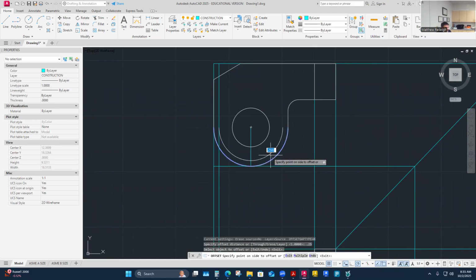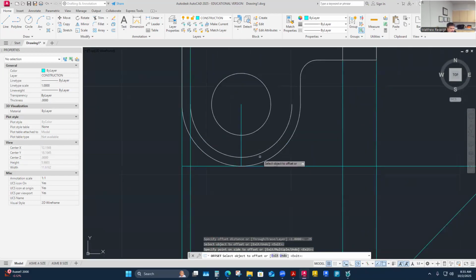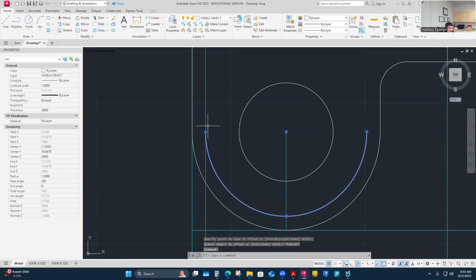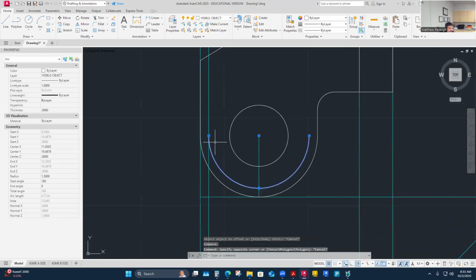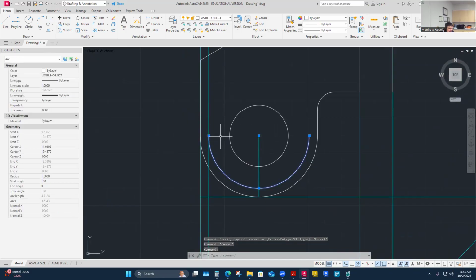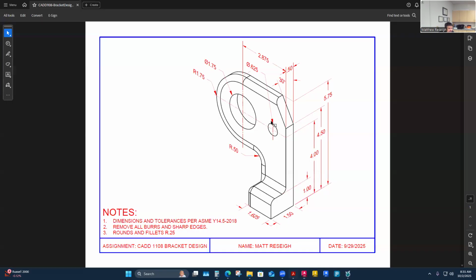And this radius, I haven't joined anything because this will allow me to just offset that in. When I look down on that radius, it'll look like that. And then from that point there, I'm going to pick up a visible line from where that endpoint is, which is across the center here, and just draw that till it hits that miter bevel there. And that's just because that's what it looks like here, right? Like I've just kind of drawn in this radius from at least the center over and around to where it hits that projection line I did, and then I'm going to put that in as visible so I see that.